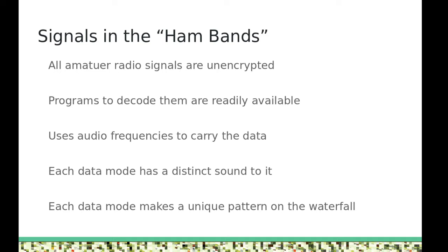Do you know why they use audio frequencies to carry the data? It's because it makes it very easy for you to get the data from your computer to your radio, which is separate. Going over the sound card just makes it really simple. You just take a cable to go from your computer's sound card into your radio, and vice versa, you use your radio's sound output to go back into your sound card.